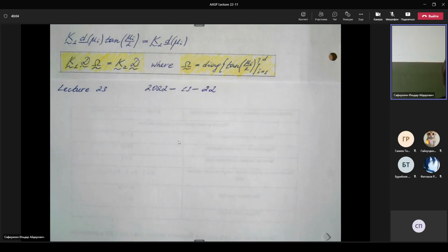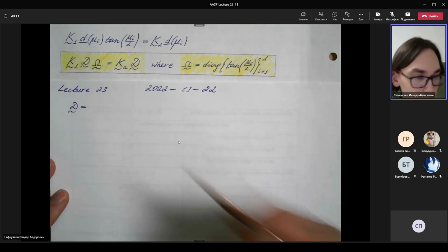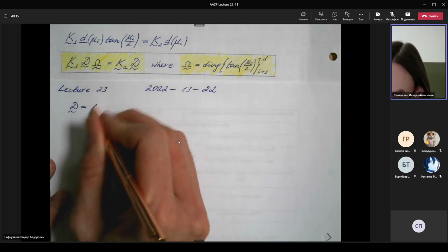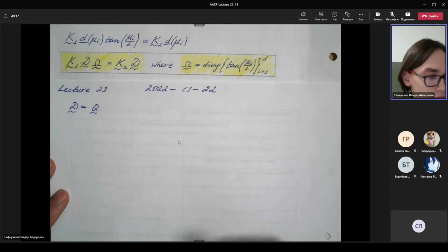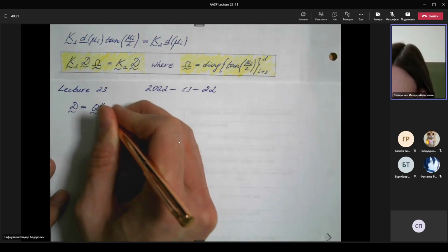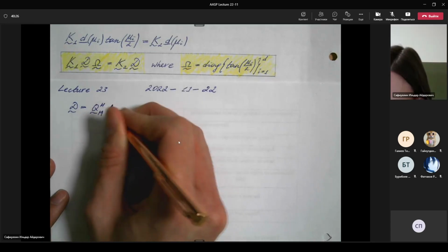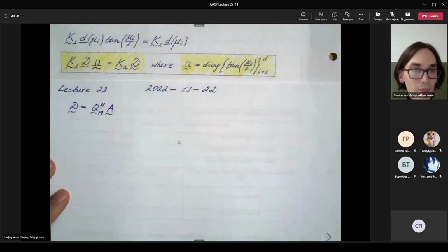And now let's write down the transformed array steering matrix D. This one is equal, one more time, to the sparse left-real unitary matrix Q of size M Hermitian times the original array steering matrix.